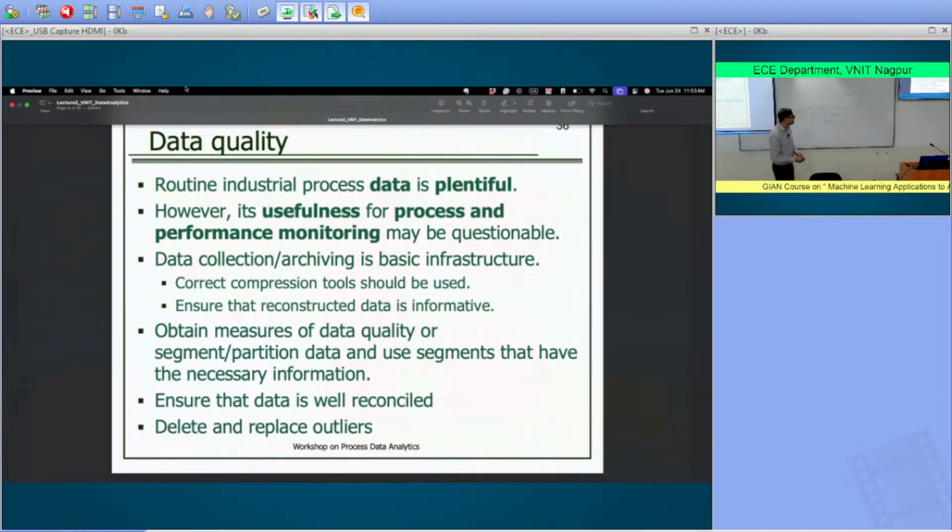As an example, let's say I'm measuring some temperature, and it varies ever so slightly here and there. There are big jumps, and then it just changes slightly. When you compress the data, you only save one value for all of that slowly varying data, and then you save more values over here where it changes, and then just one value for that data. That way, you are minimizing the amount of data.